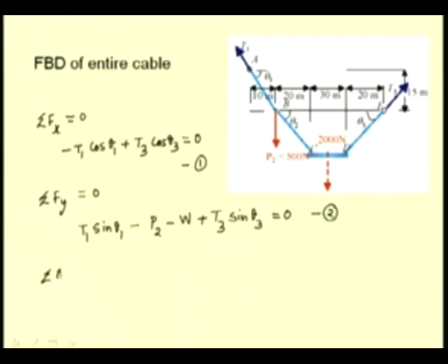Then the moments have to be 0. So, let us take the moment summation either about E or A, where we have the unknown forces. Let us take the point E and equate it to 0.